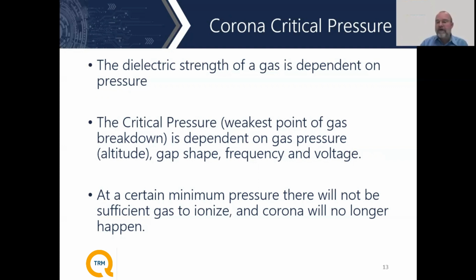Parts for spacecraft have to be launched from sea level into a virtual vacuum, so all these parts will go through this critical pressure. What's important is whether or not these parts are active during the launch as you go through this pressure point. Certain parts on the satellite are not active as we go through the critical pressure point.